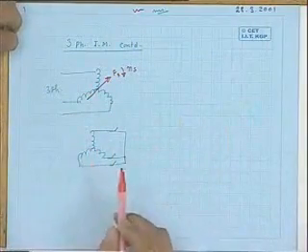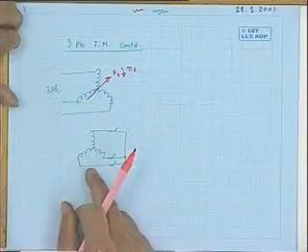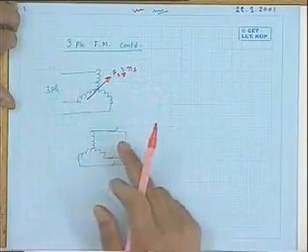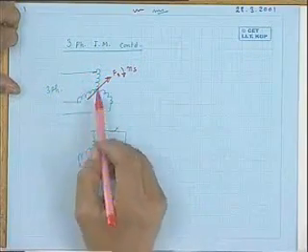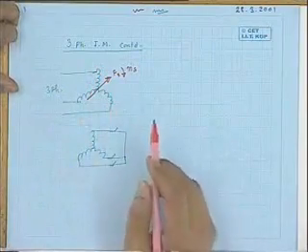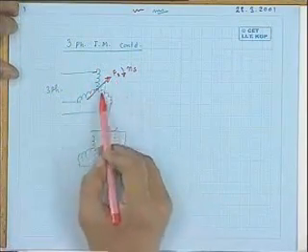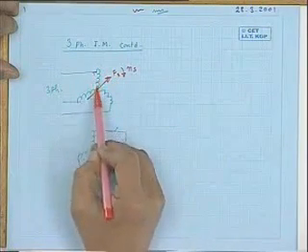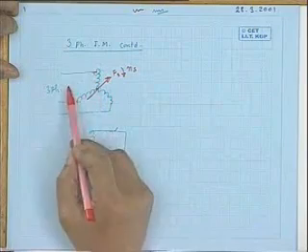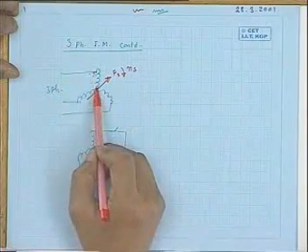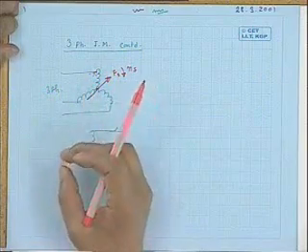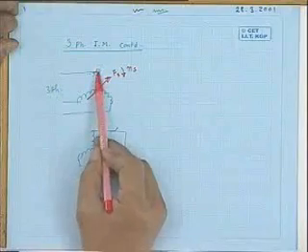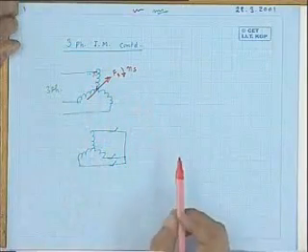And there will be induced voltage in the rotor. However, there will be no current in the rotor. So, the total MMF acting in the machine is decided by the magnetizing current, the balanced three-phase magnetizing current drawn by the stator, and the flux, as we know, will induce voltage in each phase, and this voltage will be balanced by the supply voltage per phase to satisfy the KVL equation. Is it not? If I neglect the stator winding resistance and leakage reactance drop, then this applied voltage should be equal to the induced voltage on the stator.